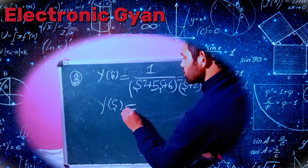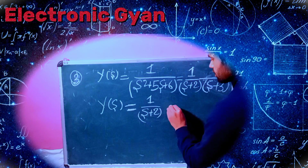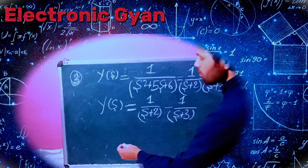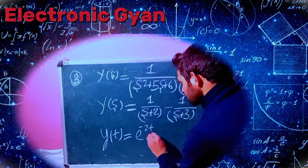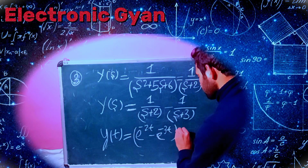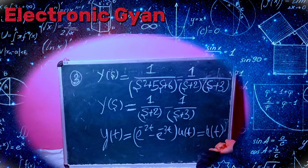Y of s is equal to, for s equal to minus 2, 3 minus 2 is 1, so this is 1 divided by s plus 2. For s equal to minus 3, this is minus 1 divided by s plus 3. Now by applying the inverse Laplace transform, Y of t is equal to e to the power minus 2t minus e to the power minus 3t into u of t. So this is my impulse response, which is the same as h of t.